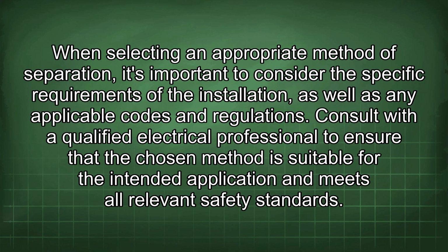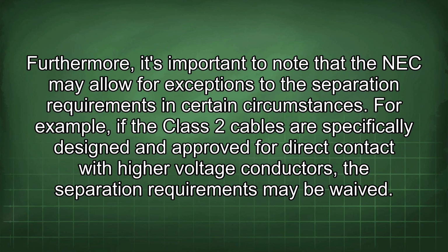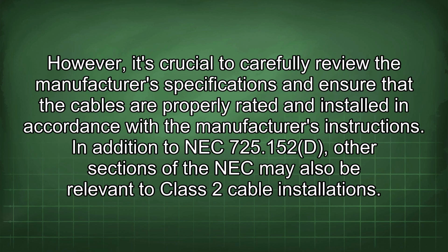Furthermore, it's important to note that the NEC may allow for exceptions to the separation requirements in certain circumstances. For example, if the Class 2 cables are specifically designed and approved for direct contact with higher voltage conductors, the separation requirements may be waived. However, it's crucial to carefully review the manufacturer's specifications and ensure that the cables are properly rated and installed in accordance with the manufacturer's instructions.